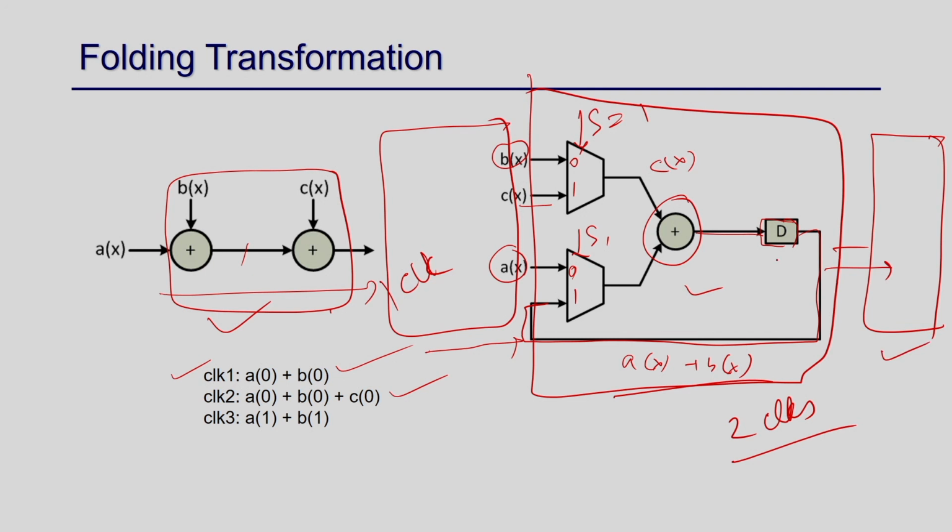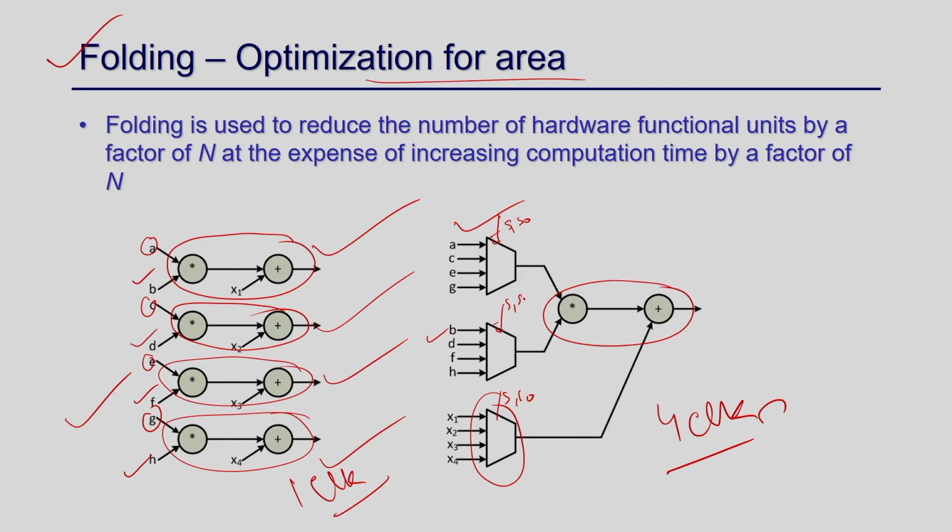But now in the modified or folded circuit, this is taking 2 clocks. So it changes the interfacing. It also creates a problem for the interface, because you have to do something here also. You have to make this circuit wait two cycles to get the input and output in every 2 clock cycles. Similarly, the corresponding output circuit has to wait 4 cycles to get the output. So something has to be changed here, which is very complex, and we should avoid that.